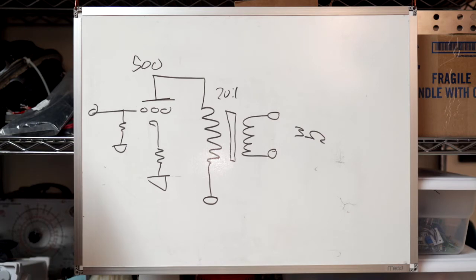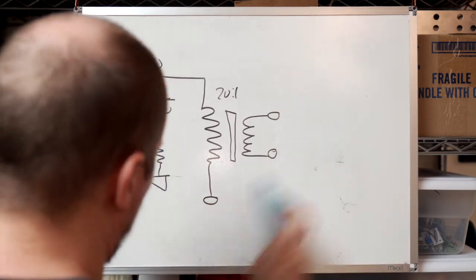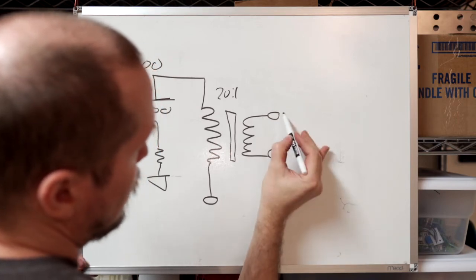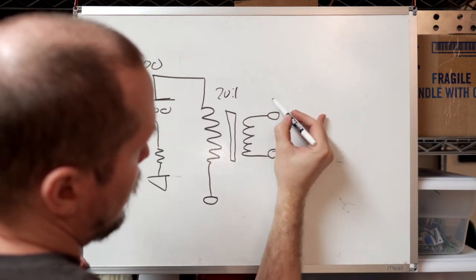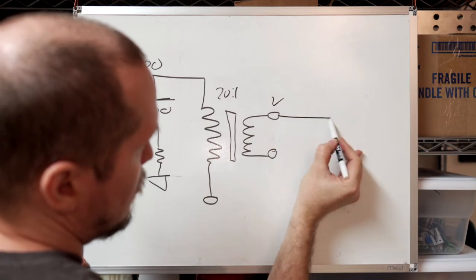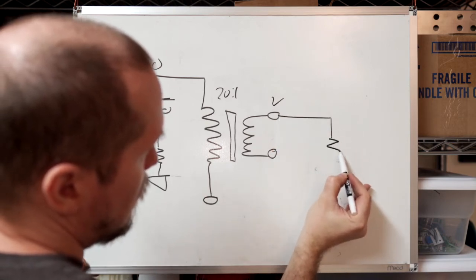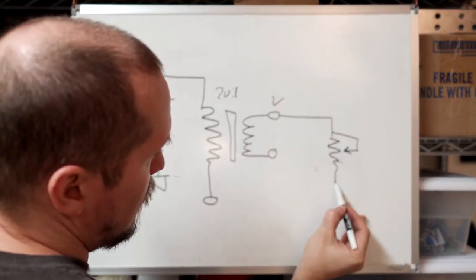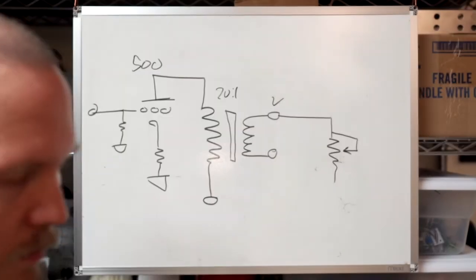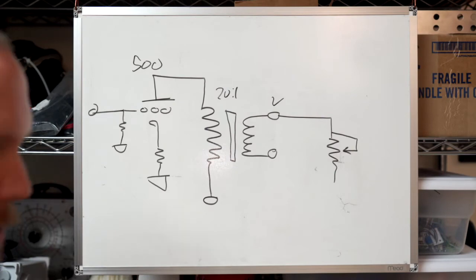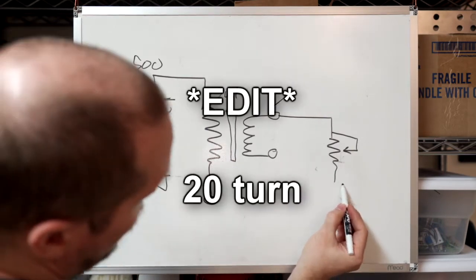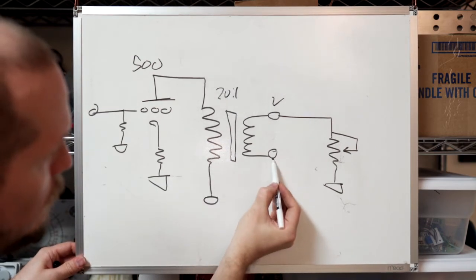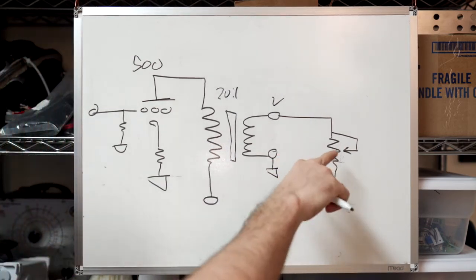And so with an amplifier like this, you really can actually just, and this is something that I do, I'll measure the unloaded output voltage right there, and then I'll take a pot like that, something low value, like I have a 5 watt, 10 ohm, 500 turn pot or whatever, and you just scroll through until you reach half the value.